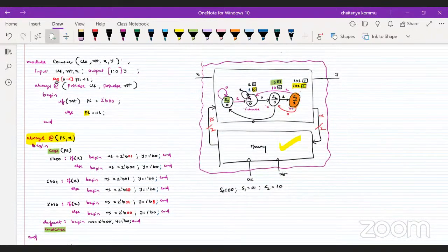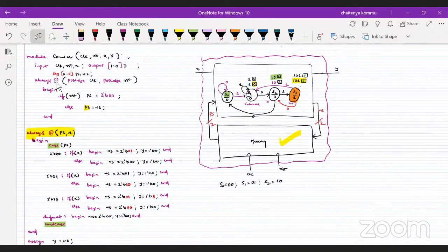Apply your concept. So we don't find any problem with the memory element, but there is a problem with the combinational part, right? So yes, this combinational part is also required. It contains two inputs, one x, the next one is the present state. This also produces y and next state, the 2-bit of next state, 2-bit of present state, right? So therefore, the always statement sensitivity list is correct, and the case statement I'm using is also true. But what about the cases?